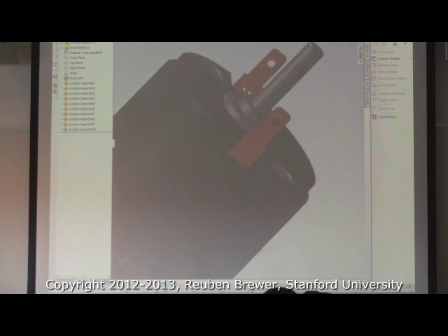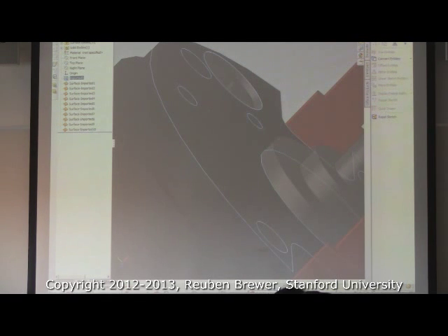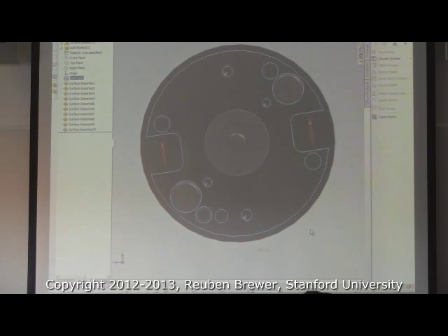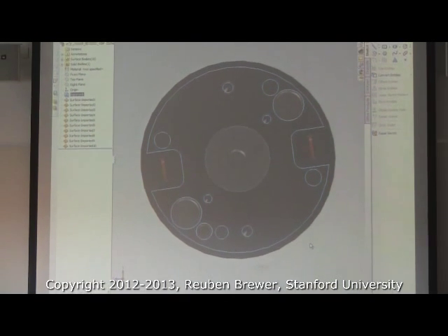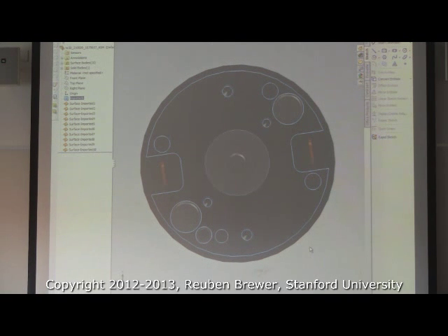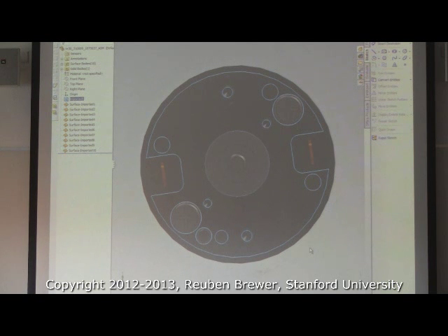Okay? Now, quick hint. This is the back of the motor, and see how it has the leads and it has the screw pattern? Never use CAD to design things, ever. If it's not on the spec sheet, it's not correct. From Maxon, from Stock Drive, to Misumi, to McMaster, every one of them has screwed me with CAD that was incorrect. Typically, they put all their resources into actual black and white, orthographic and isometric drawings, and that's the Bible.